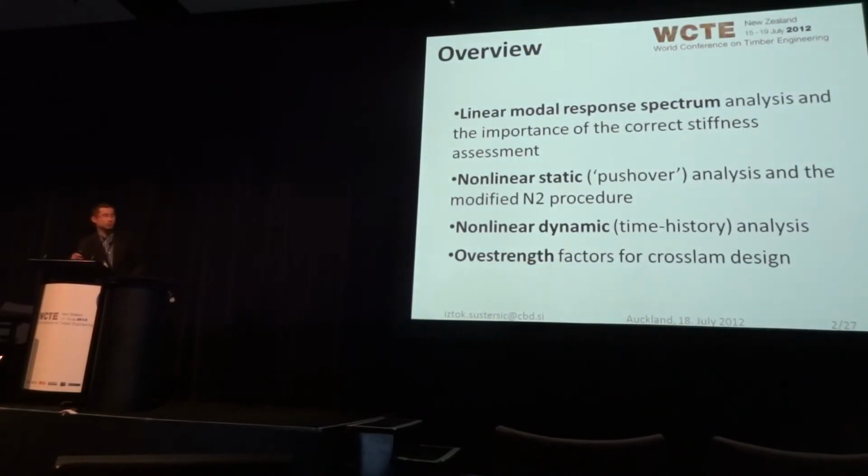Just a short overview of what I should try to show you today. We should basically go through the methods that current codes and standards offer to a designing engineer who is dealing with seismic design. So basically it's going to be a linear model response spectrum analysis, and I should try to show you the importance of the correct stiffness assessment, as Robert has just pointed out.